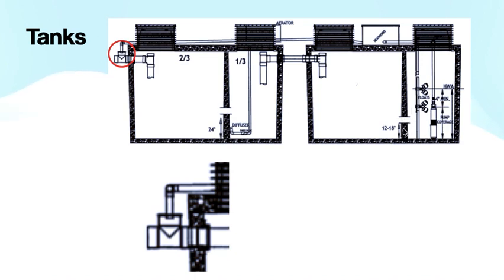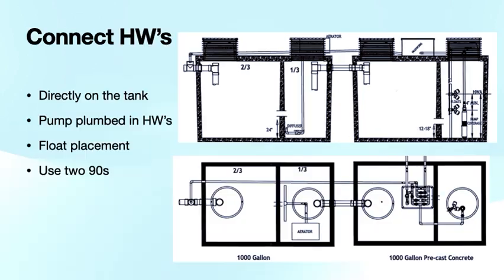In this second tank, the same hole, we only want about a foot to a foot and a half from the bottom of the tank, and so that's specific. Same kind of situation, but those are non-negotiable. That's important for the system. So specifically talking about that reverse flush headworks. On this second tank, the one that's going out to the Oscar drain field, again, we want this headworks directly on top of the tank.